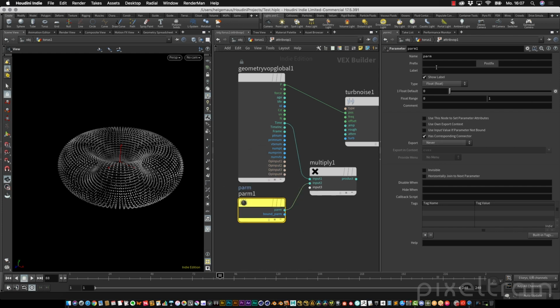Okay. Then you go into the name of this parameter node and you change it. Be aware that every node which has the same name is hooked together with the other ones, so try to get a unique name. In our case, this is the speed multiplier, and that's exactly the name I'm after, speed mult, and the label is the thing the artist from the outside sees later. So I name it speed multiply, so that's clear what's going on. The default value is 0, and that's it.